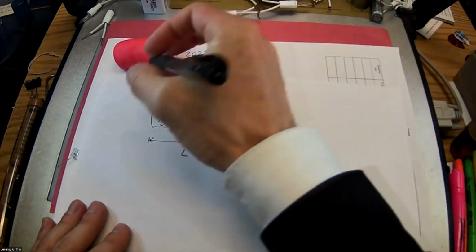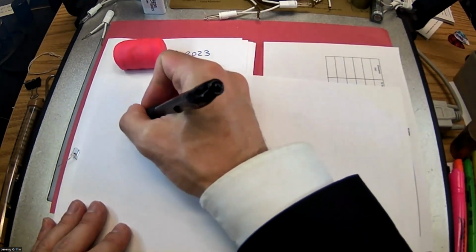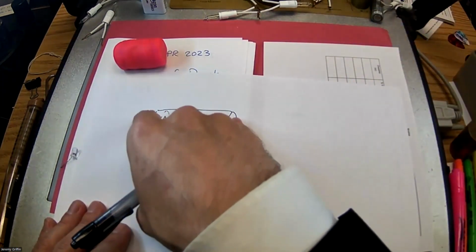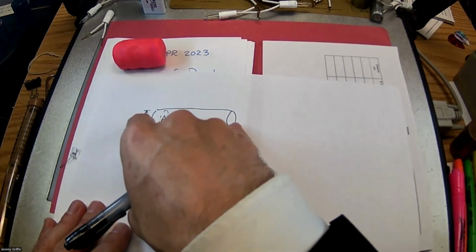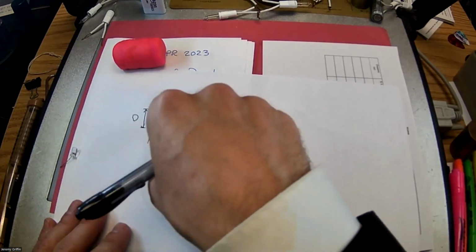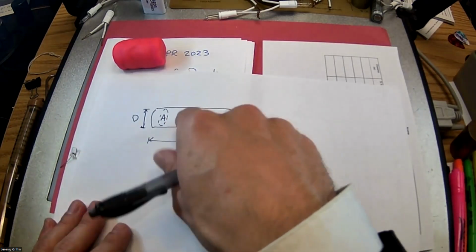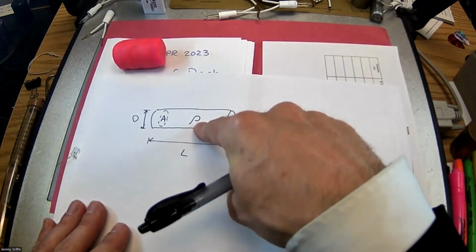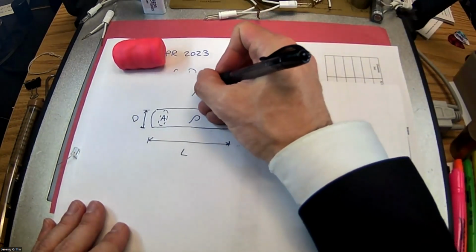One of the measurements you guys are going to do today is measure the diameter, so I'll call that D. Right. And then how much resistance from end to end? Well, the longer the wire, the more the resistance. The fatter the wire, the less resistance. Easier to push electricity through a fatter wire. But one more thing is this resistivity, and we're going to use a Greek letter rho for that. In the past, we've used it for density, but today it represents resistivity.